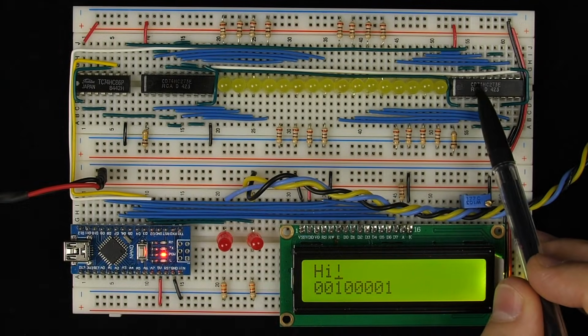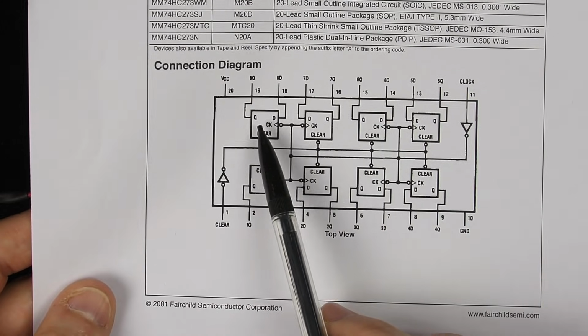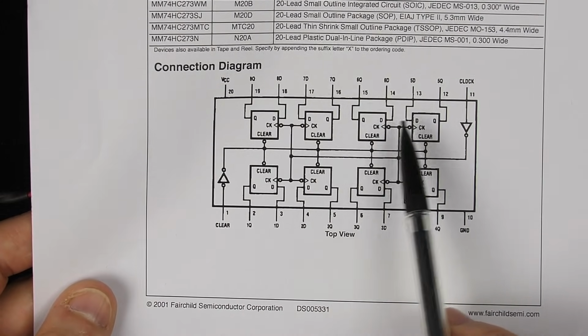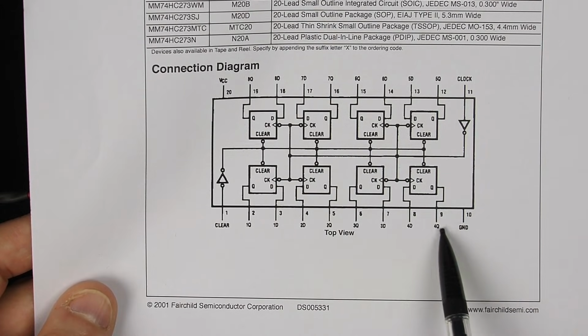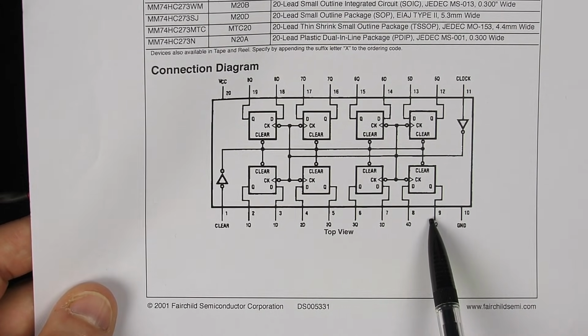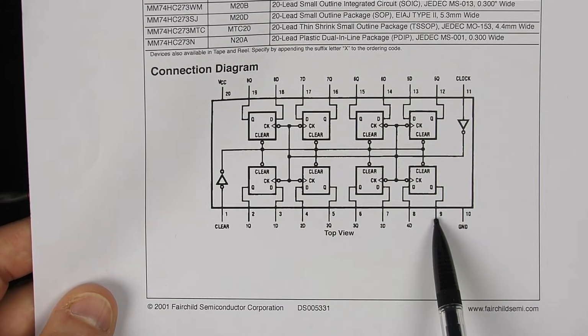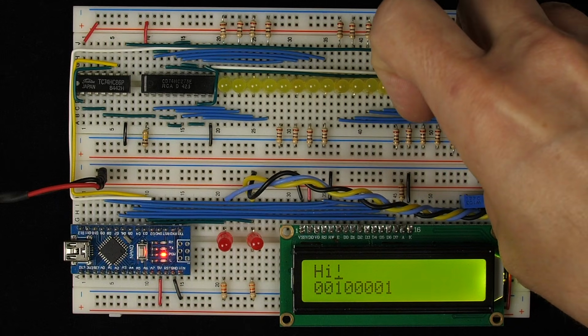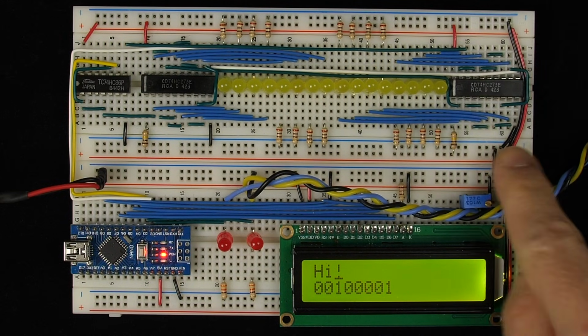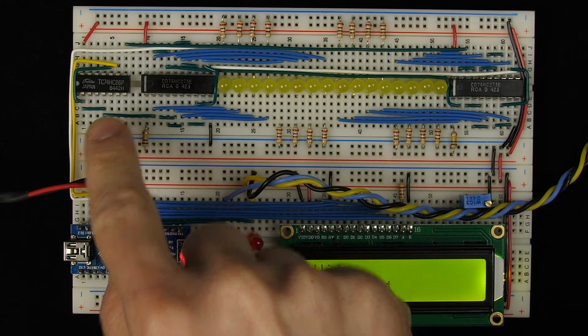And so we look over here. This is the first, so 1, 2, 3, 4, 5. So it's between this one and this one. So the output of this was going to be pin 9, and the input of the 6th one is going to be pin 7. So between pin 9 and pin 7, we should already have a jumper, and we do. That's this jumper here. So I'm going to pull that jumper out, and instead of a jumper, we're going to have to get that all the way over to one of these XOR gates.